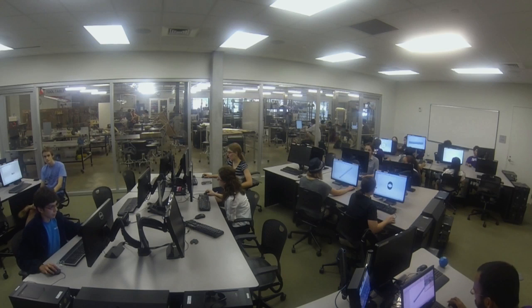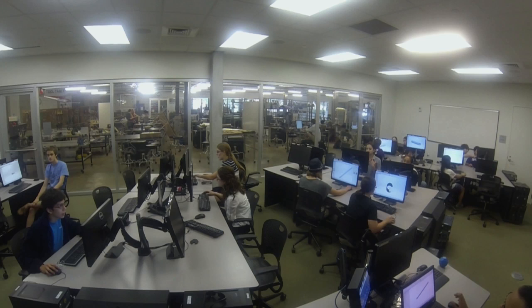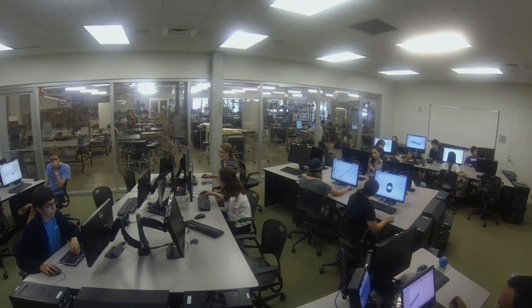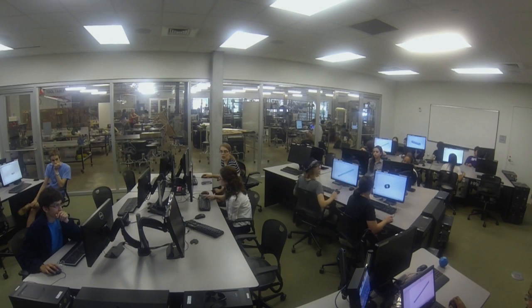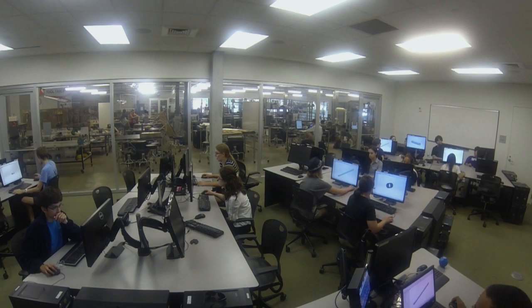All right. Okay, so to pan across the screen, if you have a mouse wheel, the easiest way, it's somewhat unintuitive, but the way that most people do in SolidWorks, just because it's faster than having to hit the keyboard, is you zoom out a little bit, and then if you move your cursor and zoom back in, it'll zoom back in around your cursor. So that's the way that most people do it if you just want to use your right hand. If you really do need to pan for some reason, I'm going to make a guess here because I don't remember, but it's either Control or Alt or one of these, and middle click. It's Control. I'm so good I got it on the first try. Control middle click will actually let you pan the part around.